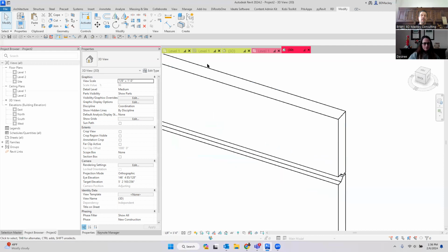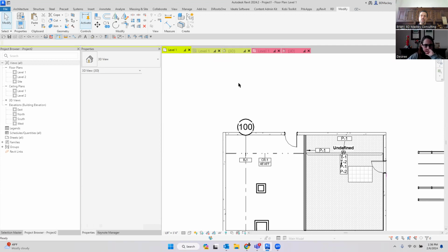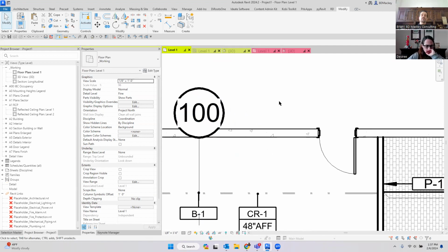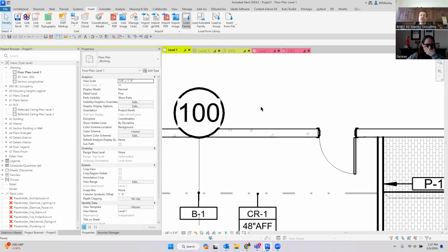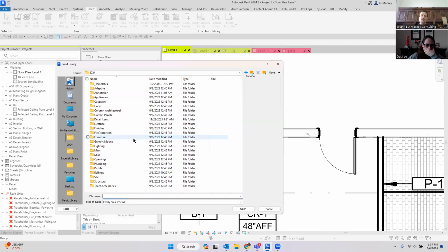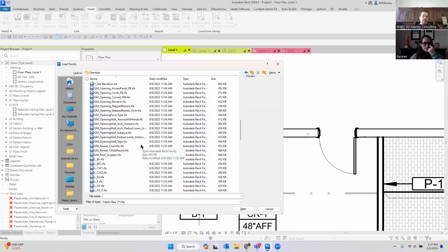So if those reveals go all the way through, I'm going to go back to the original now. If those reveals go all the way through and it is literally tilt-up construction, that's what you want to do. I suggest using parts. If we just have a whole bunch of reveals to go through the project, then no, there is no, hey, this is a great way. This is how you have to do it. Either you're using the wall reveal command, or personally for me, I'm not a huge fan of the wall reveal command. The only reason why I say that is it's got to be horizontal, it's got to be vertical, and 90% of the time somebody wants to do something at a weird angle or whatever else they want to do. So I personally have a generic reveal.